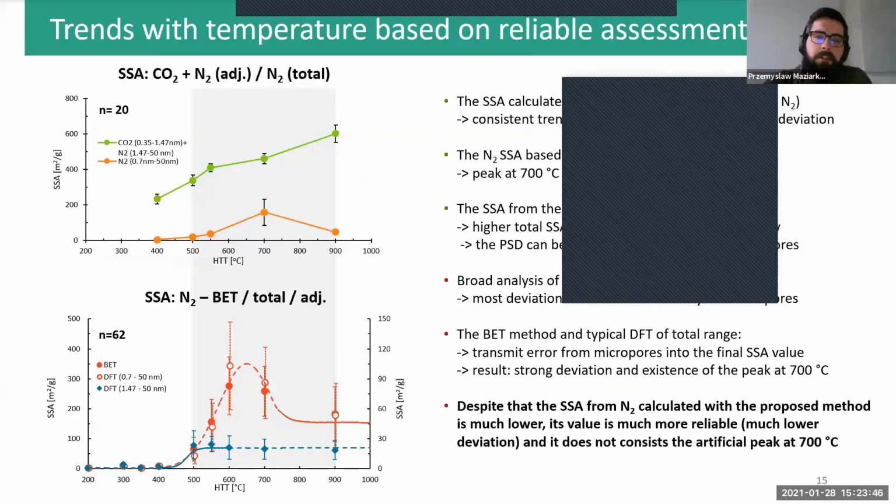Production-wise, it is quite an important parameter, because when we use larger production sites like reactors, we need to be sure that the material is fully converted at the certain temperature. That's why we have to keep a certain residence time and check the properties of the material. But after we obtain those properties in a homogeneous way, increasing the residence time shouldn't really change much the properties of the material itself.